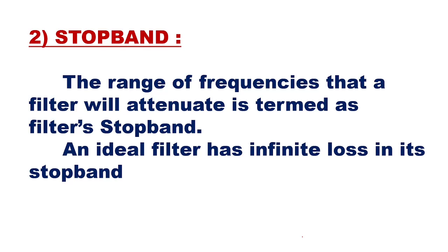So there will be no gain at all. It will be complete loss. The output has to be zero ideally. So it is infinite loss in the stop band. The filter will not process signals of those frequency ranges which fall in the stop band.